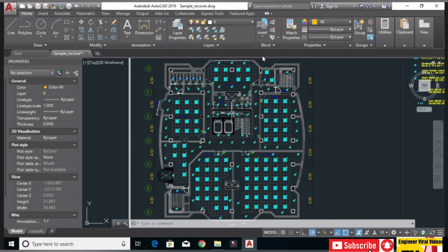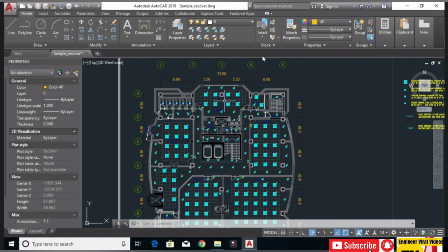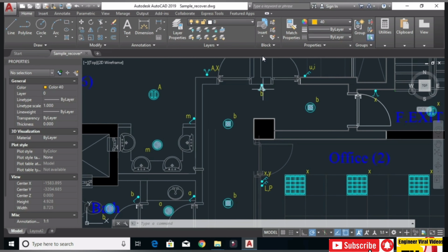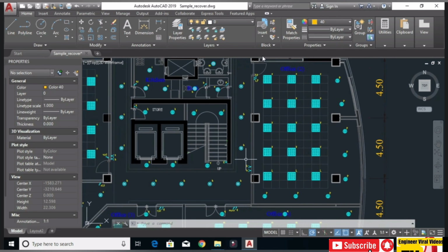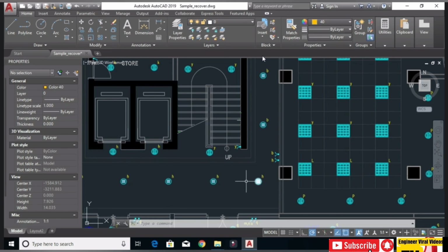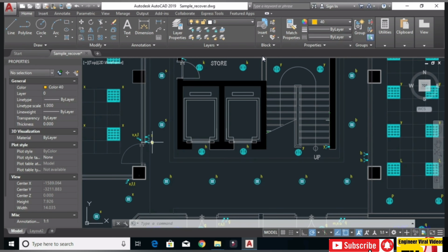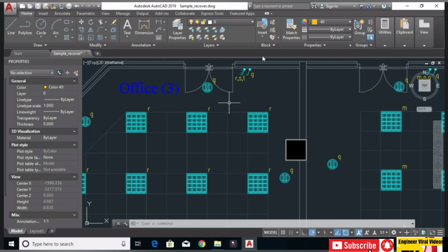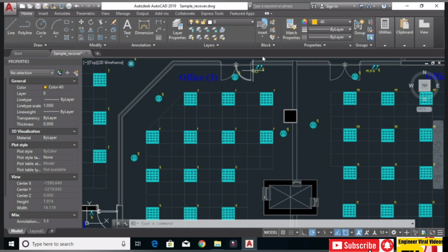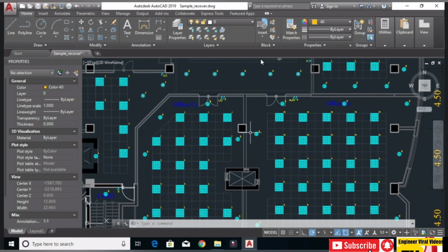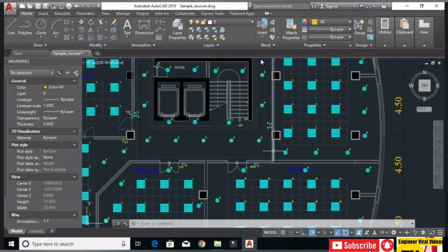After we finished distributing our lighting fixtures and switches, as you see here, we put this two-way switch as we said in the last lecture. See here, this is for BH also. Here the second way switch, and also here we put one-way three-gang and one-way switch. This is for GM. I will attach this drawing, you can check by yourself.